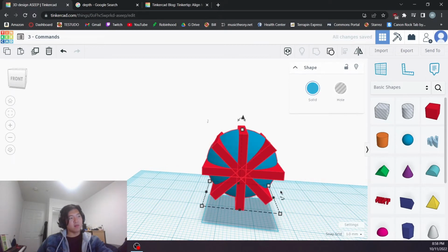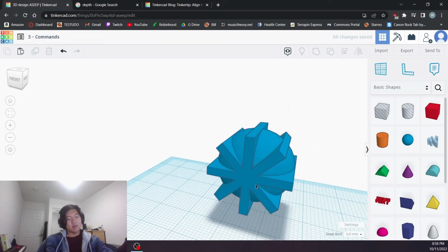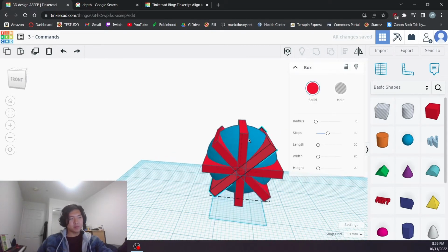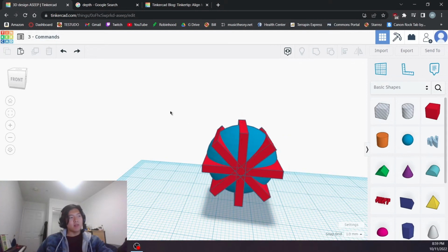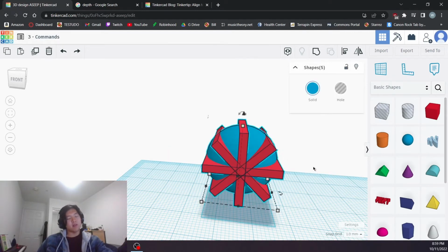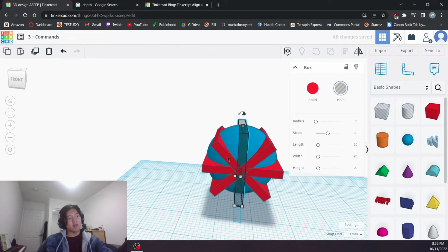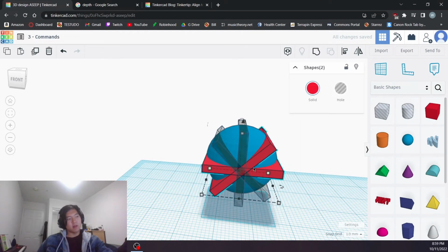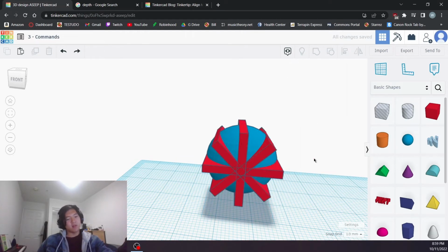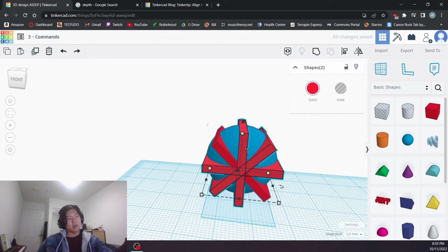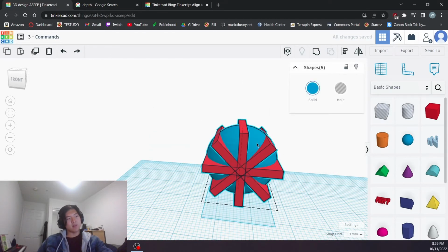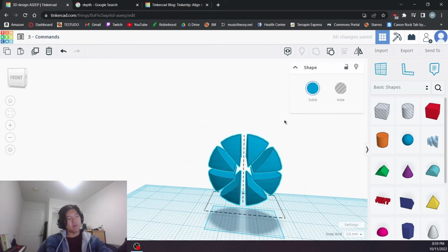And then, you could group this. Actually, I think holes would be interesting. Since you have to click and drag, you don't want the sphere, right? So instead of making these holes individually, you can hold shift and click. So 1, 2, bam, they're both highlighted. Let me just undo everything. So hold shift, click, like this, bam, all 4 highlighted. Or if you highlight everything and then shift click the circle, it will undo that. So just make them holes and then group and let's see what we get.